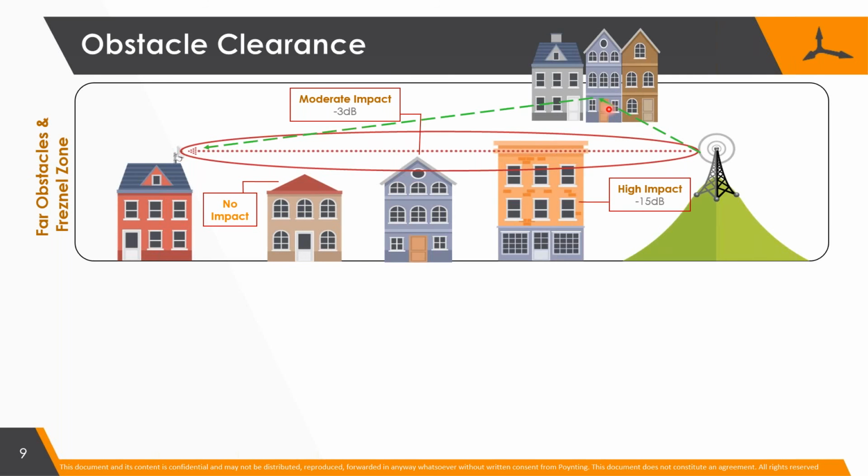The one aspect one has to take into account in a city environment is that there are also reflections. Reflections can often give you still reasonably good data links, even if you've got a building in front of you, because of course you could be receiving that signal. When we get to the choice of antennas, you'll see this is quite important. And also when you talk of MIMO, in other words, multiple input, multiple output, this is sometimes quite useful, because it can actually increase your data, since you've got more than one path between the transmitter and the receive antenna.